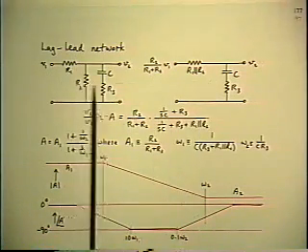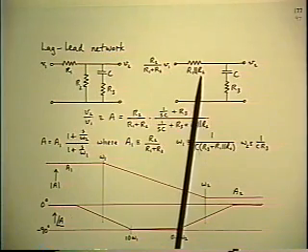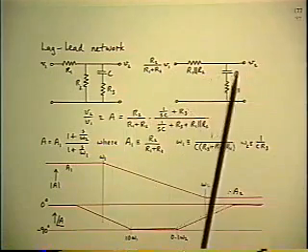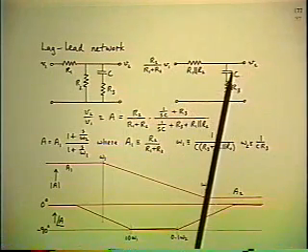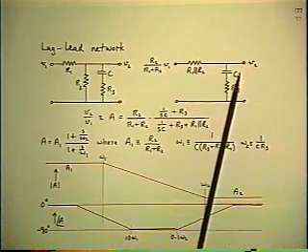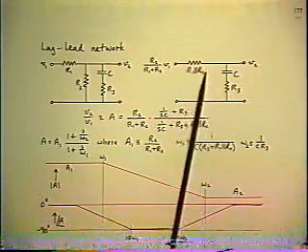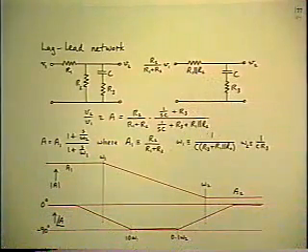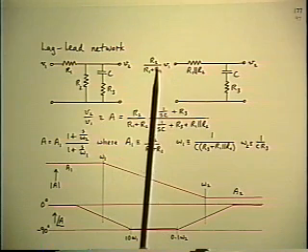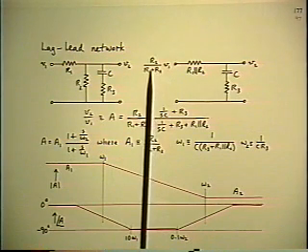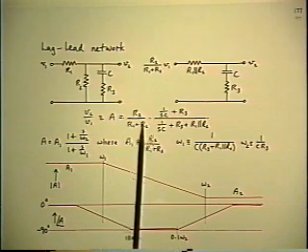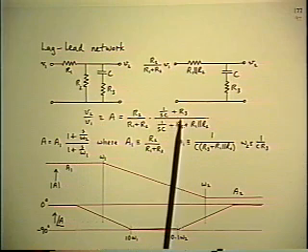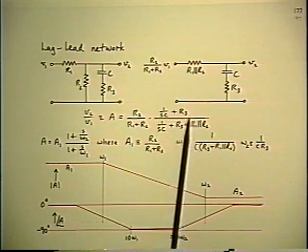So we absorb the R1 and the R2 into the Thevenin equivalent, which reduces it to a single loop circuit, and we can then write the answer in one line as a voltage divider. So the bottom branch of the divider is 1 over SC plus R3, and the denominator is the same thing plus the top branch, which is R1 parallel R2. And the resistive divider is already explicit as part of the Thevenin equivalent, which comes out as a factor in front.